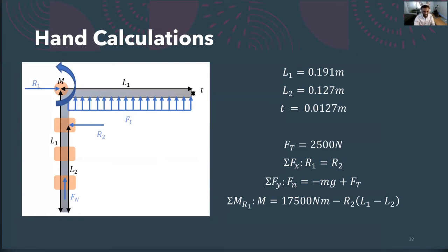When a pure machine design approach is taken, we can analyze the same component with the same force to give us an idea of what the yielding stress could be. Here, we would be looking for the forces labeled R1 and R2, which indicate reaction forces in the component when a force is applied upwards on the bottom protruding portion of the bracket. These reaction forces would be from the bracket being pushed up against the mounting wall and pulled up against the fastening bolt, respectively.